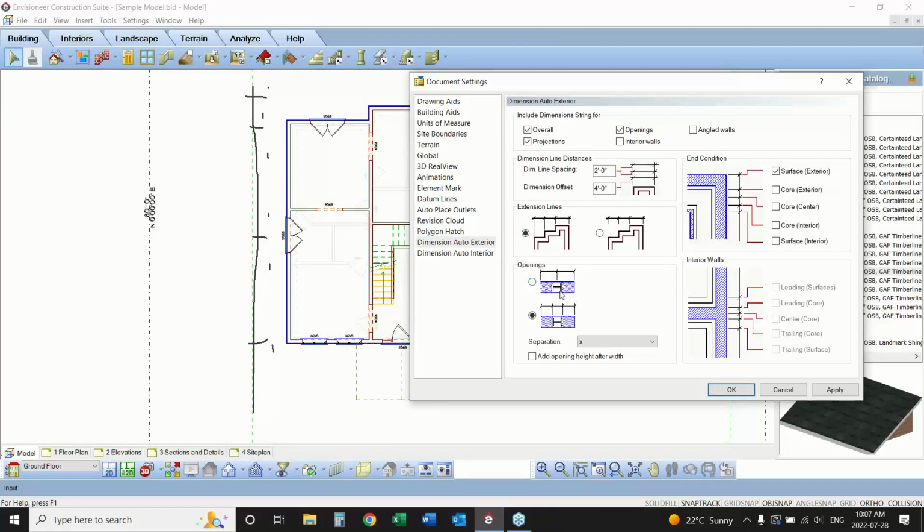When you go to dimension the openings, do you want the openings to dimension to center line, or do you want them to be either side of the window itself or the door? So really that depends on your audience. If you're looking for your bricklayers, they're going to want to know either side where they're stopping and starting, and when they're placing in that window, they're going to want to know those dimensions. But generically, when you're showing it to a client and maybe they haven't even picked their windows yet, we haven't confirmed sizes, you might go to center line. So it depends again on the audience.